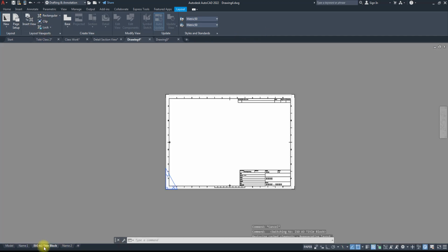So if I come to this place that doesn't have a viewport, I can come all the way to my layout viewport and I click here. These are the different ways you can create viewports. Okay? We can do a rectangular viewport, polygonal viewport, or by object. So we're only going to look at these two. So if I say rectangular viewport, then it tells me I can just create a rectangular shape and I now see this. Okay.